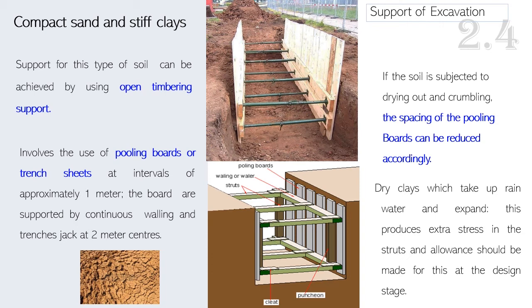Dry clays may take up rain water and expand. This will produce extra stresses in the struts, and allowance should be made for this at the design stage.